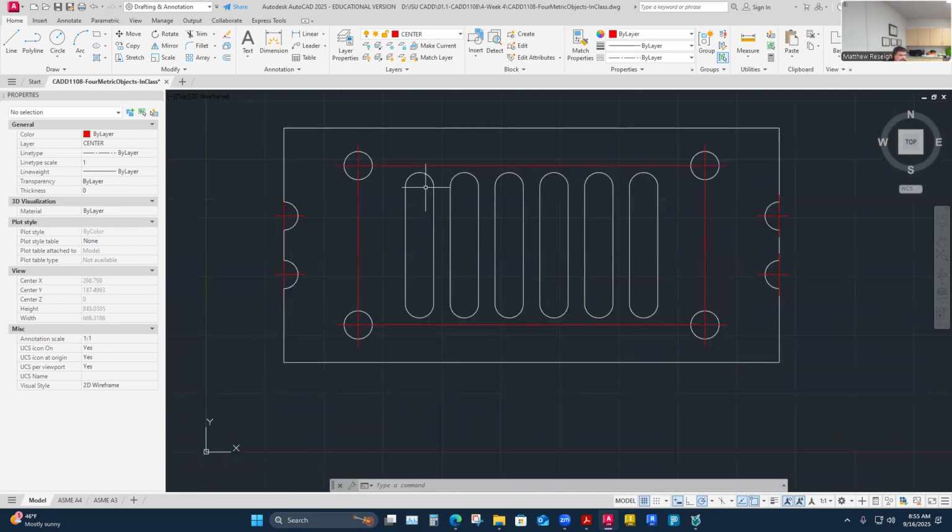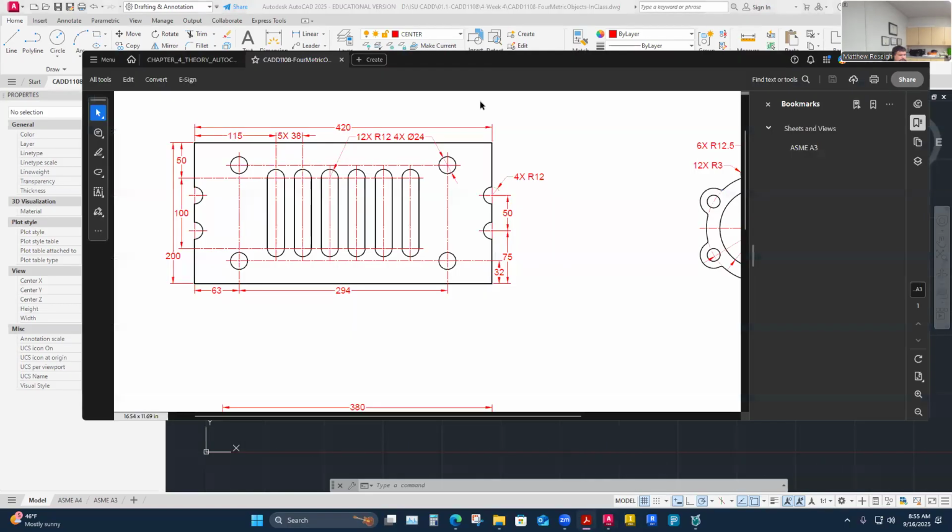And then we need to do maybe one of these and then just pattern them across. So I've got to do a radius feature like this that still needs center line alignment stuff. If you'll notice on the drawing, I'm pretty much replicating what's on there. I've pulled those ones across. You can tell that when it's a dimension drawing, I have to additionally extend those center lines out to the dimension line. That's going to come in our future when we're dimensioning. Right now, we can just leave all ours terminated as we just finished.